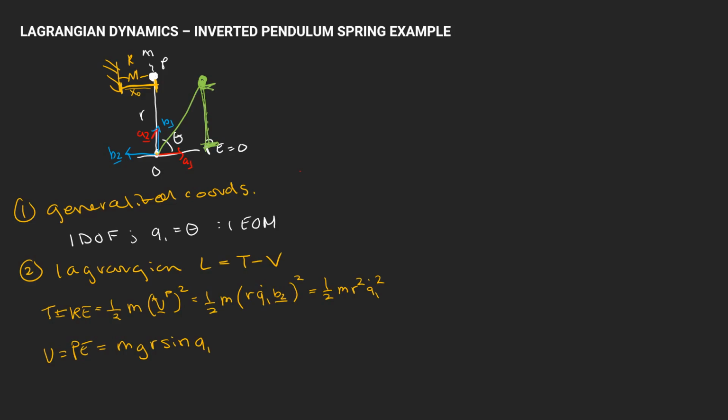And so we can think of our spring displacement, let's take this orientation of our pendulum here, as this distance here in the x direction, because again, the spring can only apply horizontal forces. This is the displacement of our spring. And so we can write this as 1/2 k, and then this displacement we can write as r cosine q1, squared.